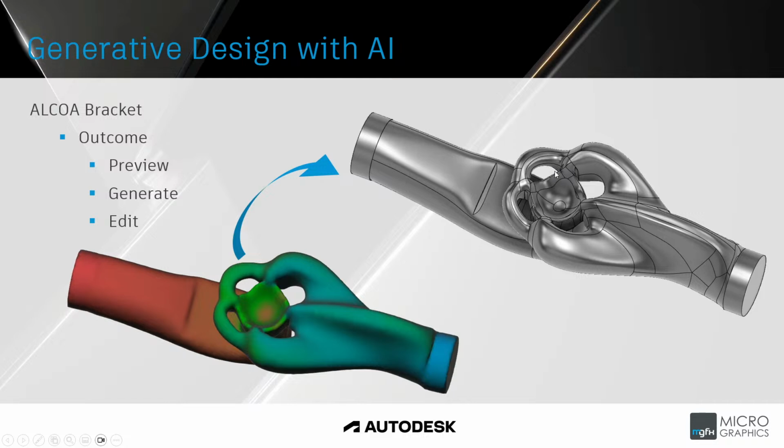You may find that manufacturing these cavities are going to be difficult. So you could fill those in, bearing in mind that is going to adjust or change the fluid flow. It may no longer be optimal, but you can go in and essentially change what represents the cavity of the valve or component that you are designing. You would then use this to create the body of, in this case, the valve, the geometry, the solid geometry around this to create that internal cavity.